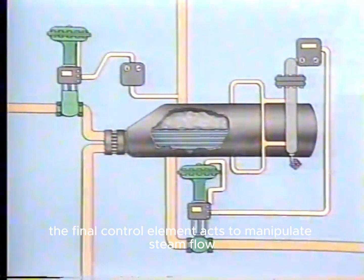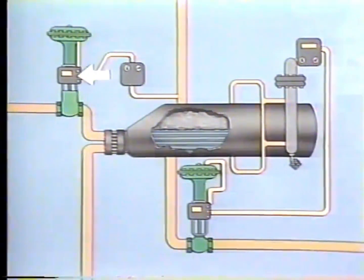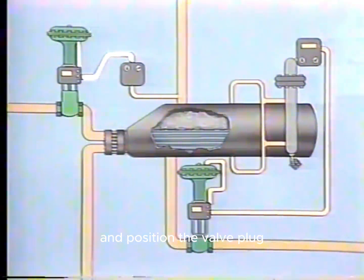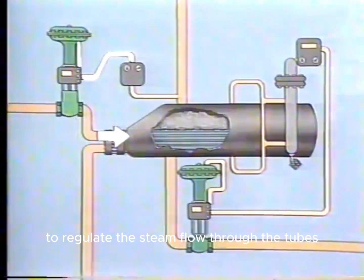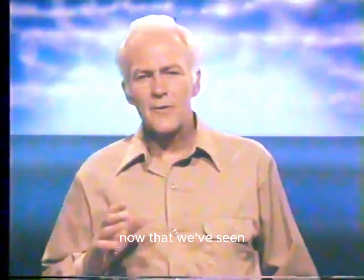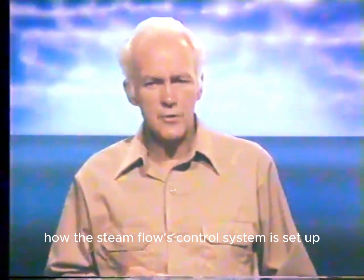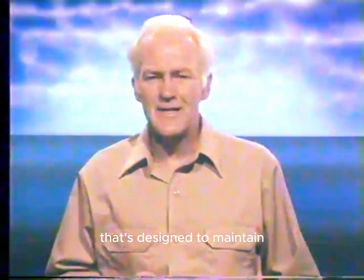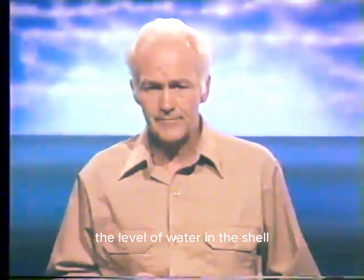The final control element acts to manipulate steam flow. The positioner and actuator respond to the signal from the controller and position the valve plug to regulate the steam flow through the tubes. Now that we've seen how the steam flow's control system is set up, let's take a look at the control system that's designed to maintain the level of water in the shell.